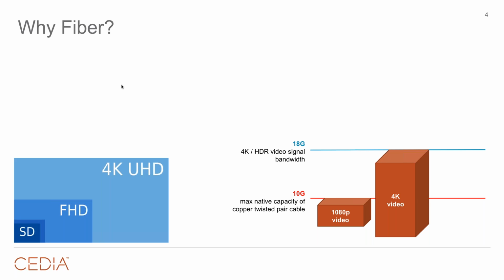And we also know that copper, through things like HDBaseT extenders and different types of twisted pair extenders out there, has historically had the bandwidth, the data rate capability to move those signals effectively. Now, we'd max out at about 330 feet or 100 meters. That's kind of the spec that we operate within in the twisted pair world, but that handles the majority of the installations.